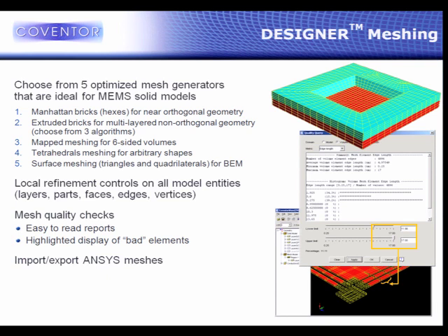You select that part and bring up the mesher settings and set the mesher setting as 6 on that part, and that part will get a nominal size of 6. Everything else is 8. And you can do that right down to faces, edges, or vertices. So it's really quite powerful. A lot of people aren't aware that that feature is there, but it is available and very useful.